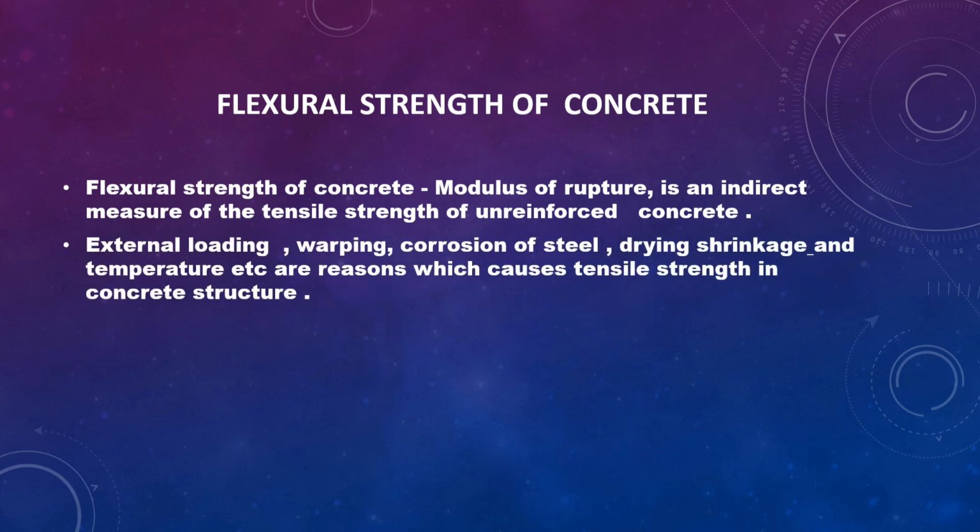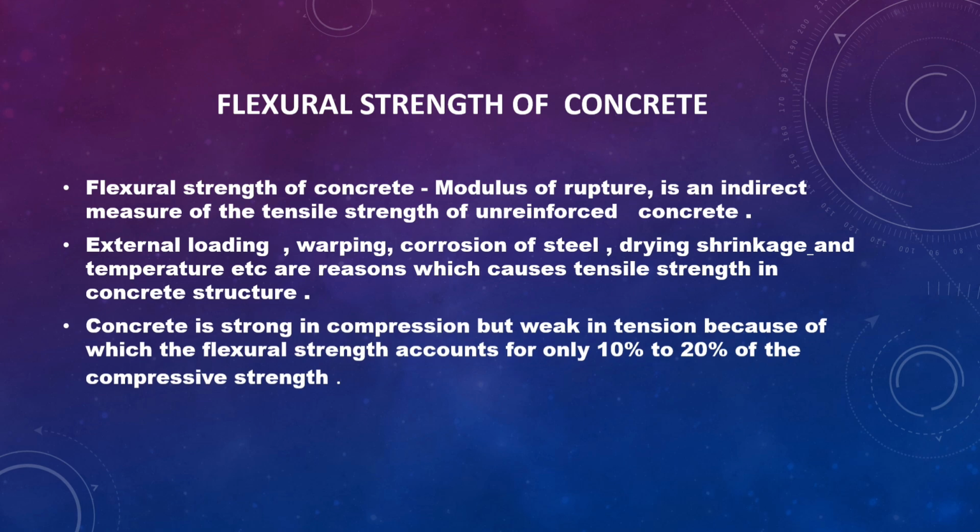What are all the factors which induce tensile loads in the concrete? External loading, warping, corrosion of steel, drying shrinkage, temperature effects, etc. are the main reasons which cause tensile stress in the concrete structure.